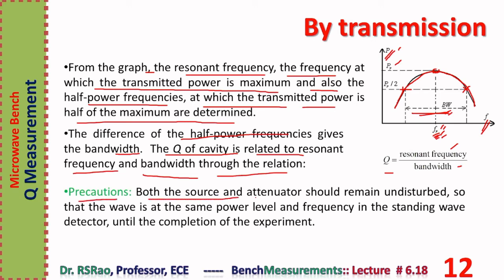Precautions. Both the source and attenuator should remain undisturbed so that the wave is at the same power level and frequency in the standing wave detector until the completion of the experiment.